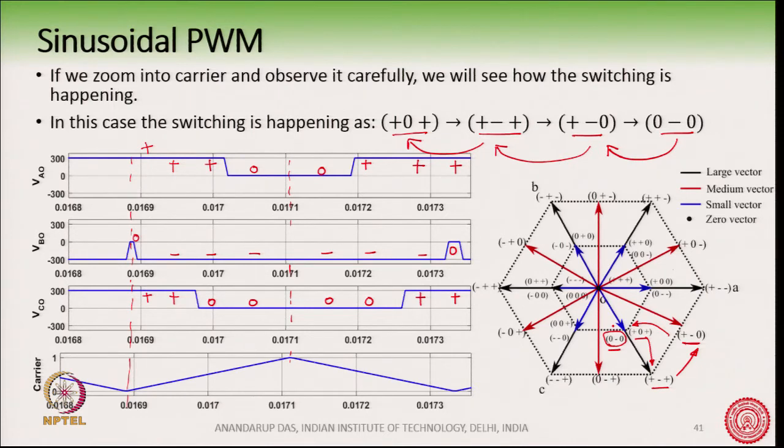This is very consistent with the space vector PWM strategy that we had developed earlier for a 2-level converter, but now our center or pivot vector is here. This is the start and end vector. As we said, these are the 6 pivot vectors from which the switching starts, and this is an example of such a switching.